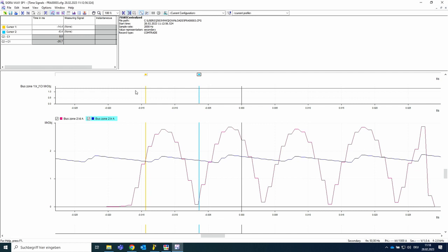Between the yellow and the blue line we have 8 milliseconds? Yes, the state time of 8 milliseconds is for 50 Hertz. Of course, we are testing here with a 50 Hertz system. For 60 Hertz, it would have been 6 milliseconds. And after the state time of 8 milliseconds, we will have a measurement window of 6 milliseconds. And within the 6 milliseconds, we need 4 threshold exceedings.